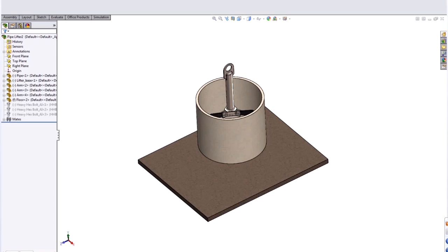In Motion, we'd be able to model that movement, right? See it drop. We'd be able to make a prediction of the load transferred at the collision point, but nothing's deformable or breakable in Motion, so it's going to treat everything as a rigid body. The complete way to analyze that sort of situation, an object dropping onto something else, is a nonlinear dynamic analysis, which is possible in SOLIDWORKS. That's in Simulation Premium. However, it can be very challenging.